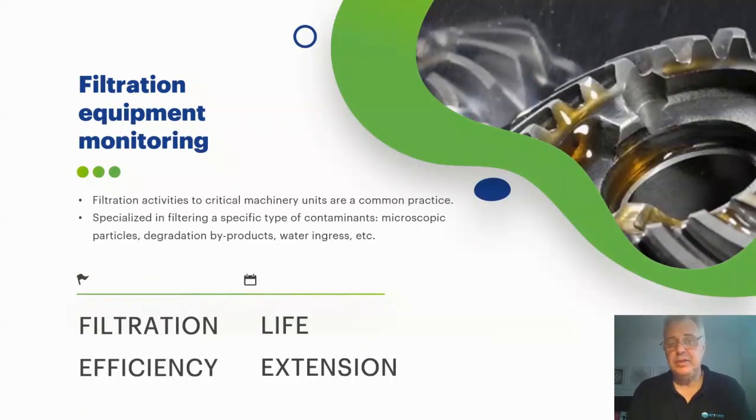About filtration actions. In this case, we could be talking about offline filters, where punctual interventions at a given moment in time are necessary, whether it is for solid particles, for water, for degradation byproducts. Here, online monitoring is valuable for knowing immediately not only what the values are to see how the lubricant is, but also if filter efficiency is correct, or if it needs to be changed, or if it could last longer.